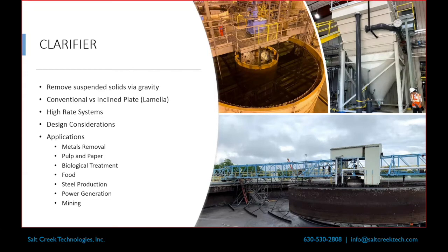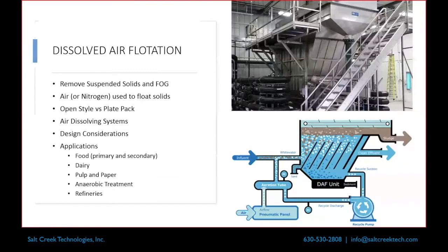Now, you don't want it to the point where it's reaching the top of the plates, obviously, because it's not going to be clarifying anymore. But in general, I'm okay with leaving a fairly decent sludge bed, maybe a foot or so, depending on the geometry of the system. Any other questions on clarifiers?